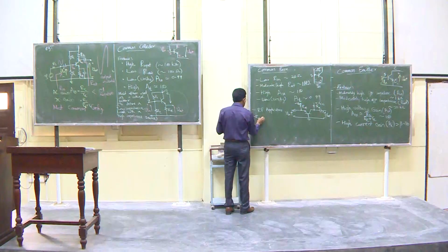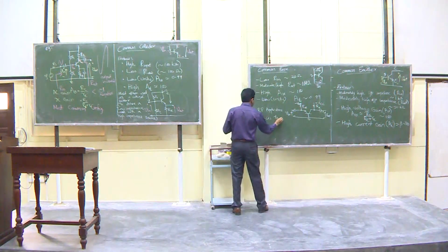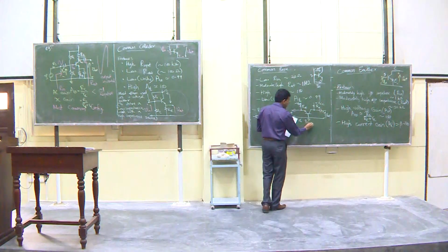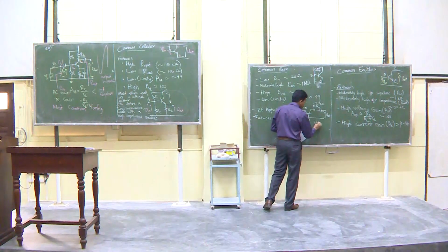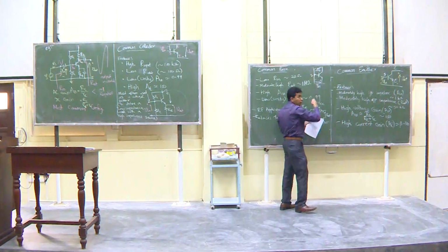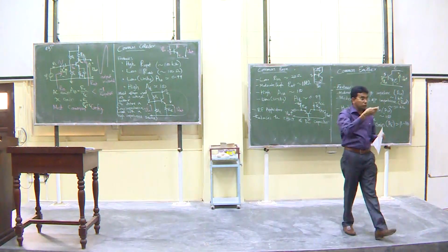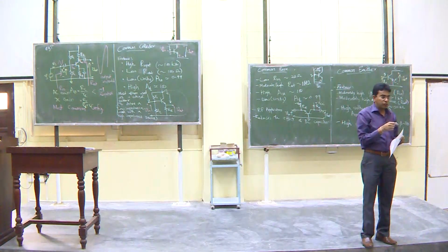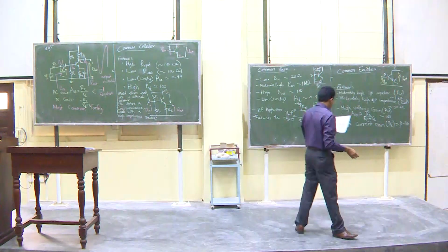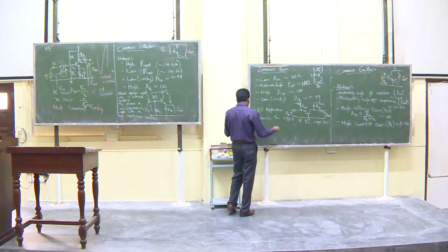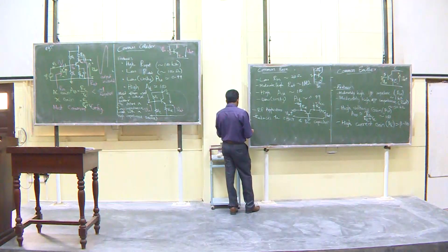It reduces the effect of the base collector capacitor. Now, between the base and the collector, in addition to the diode, at high frequencies the capacitance between them is considered. So under this configuration, the effect of that capacitor is reduced, and therefore the bandwidth can be increased.